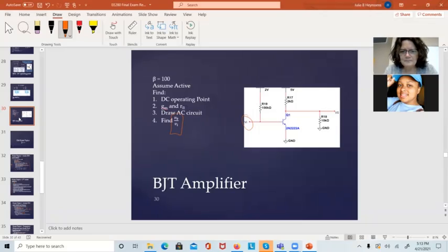So in the circuit that we had for that problem, would we find that ratio by doing a voltage divider or something? Well, similar. Basically you have to do that small signal circuit model. You've got R pi, and you've got your little current source here, and you know that VN is tied directly to the base.